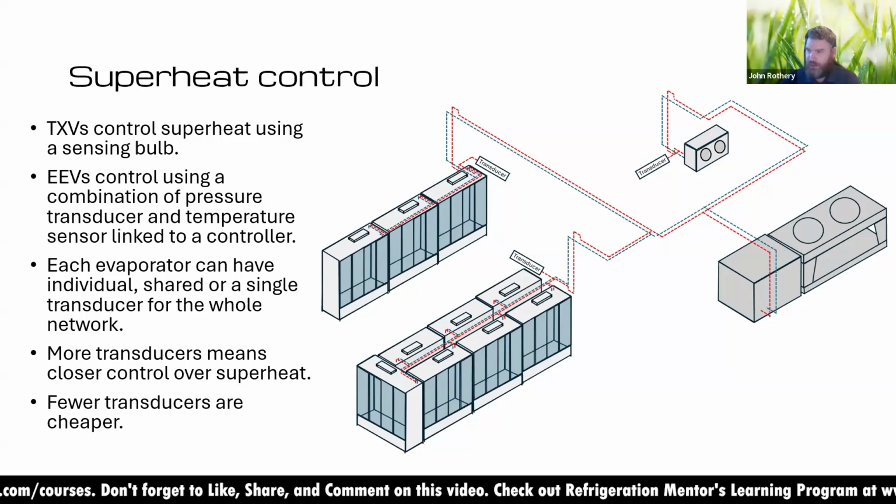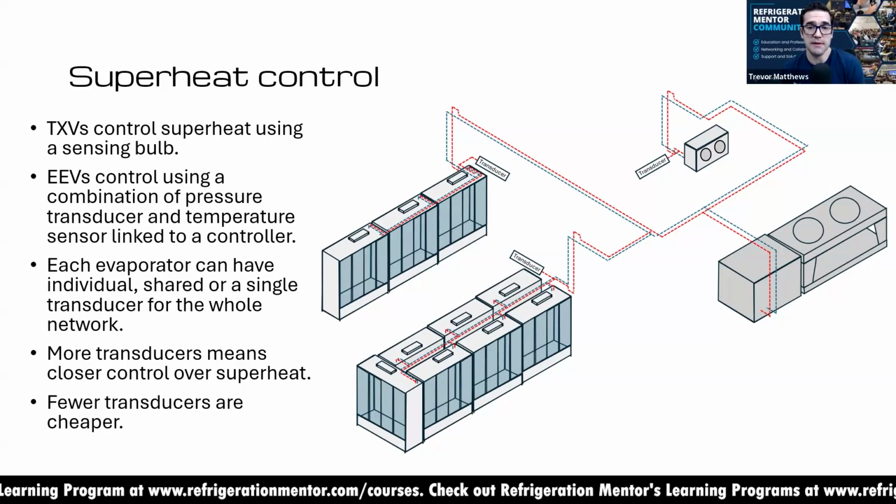So you've got the manual fallback, and also you've got the transducer fallback, haven't you? If the transducer fails, you set it to say 20 bar, the transducer's off, but you still see that reading on your controller, so it sort of hides the issue. If you've got multiple transducers, you can compare one case to another, and it's pretty apparent that it's not moving and it's just flatlined on your graphs. Yeah. And that's it. It's easier for troubleshooting. It is more upfront cost for the end user.